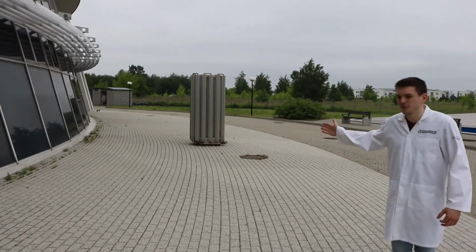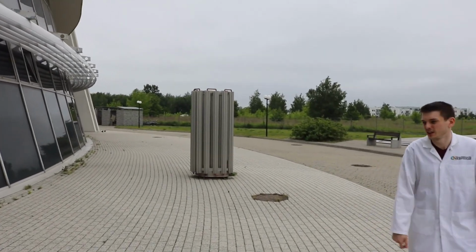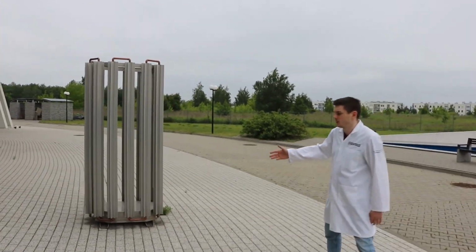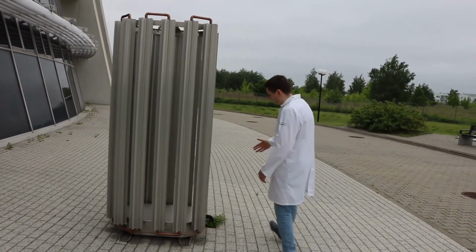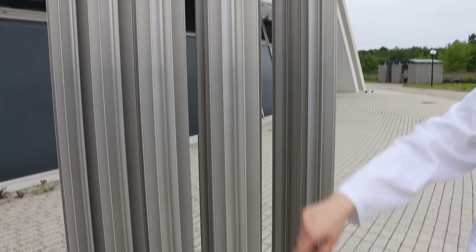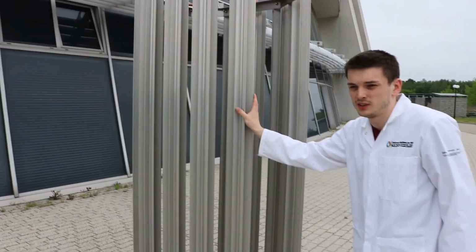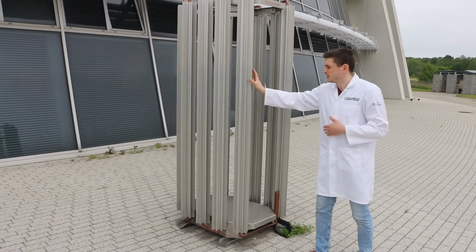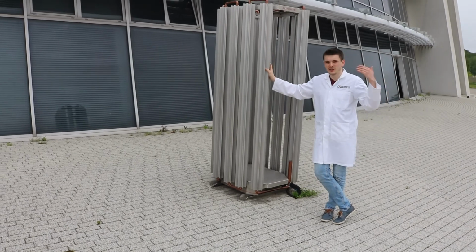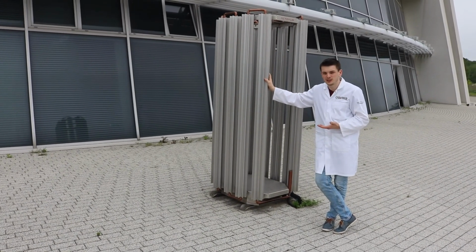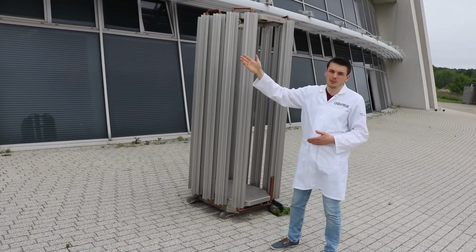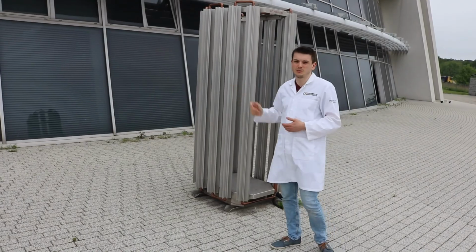Guys, this is the evaporator of this heat pump that I promised to show you. What it does, the low temperature liquid is delivered here and it goes all the way across, up and down in this radiator. The liquid is much colder than the air outside, so the heat from the air is transferred to the liquid and it evaporates to gas. And it goes right back to the main building, to the compressor, as I told you before.